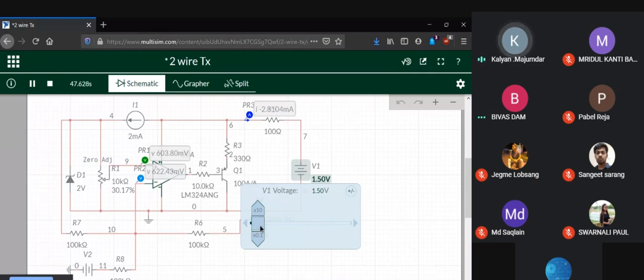So obviously it's independent of voltage, but there is a minimum voltage limit and a maximum voltage limit. The maximum voltage is what the device can physically withstand, and the minimum voltage is limited by the circuit. For example, here it will not work below 2 volts, because the Zener needs more than 2 volts to work. So what you can note is that at 5 volts it is at 3.99, and even at 4 volts.